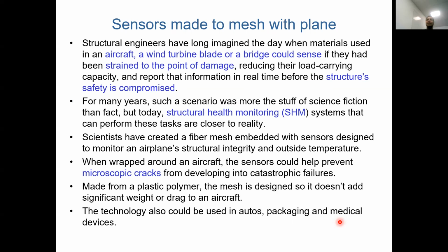You might have seen in the city center, big old buildings, they attach a piece of wire at one end and the other end. And in the middle, they put a kind of tiny meter. If that building is falling or the crack is getting bigger, the load will be bigger, and it will be shown here. So it records the reading.